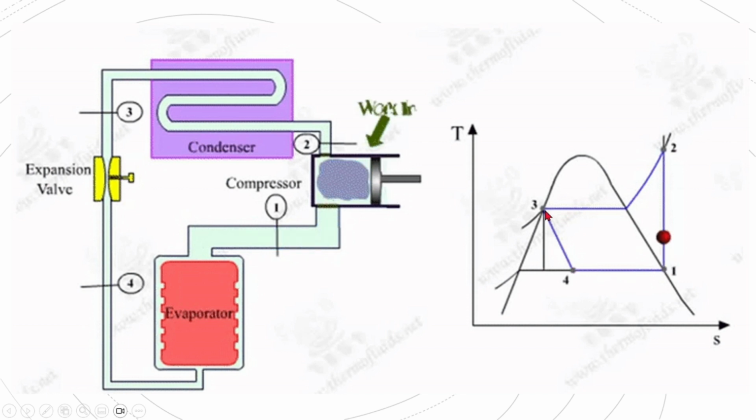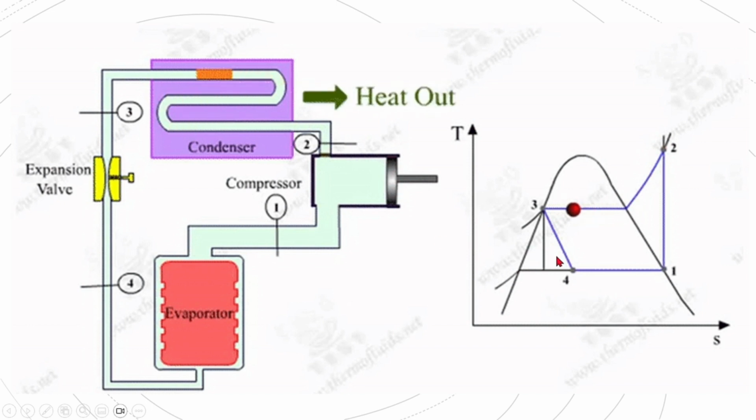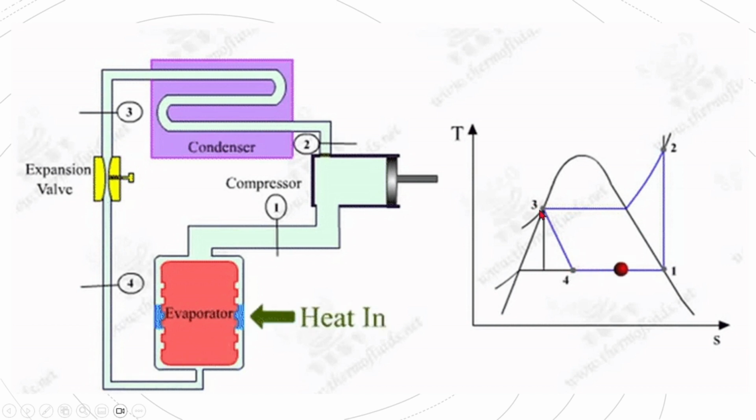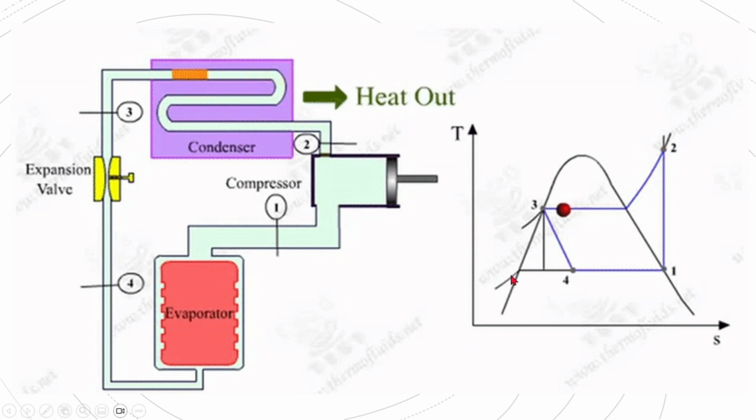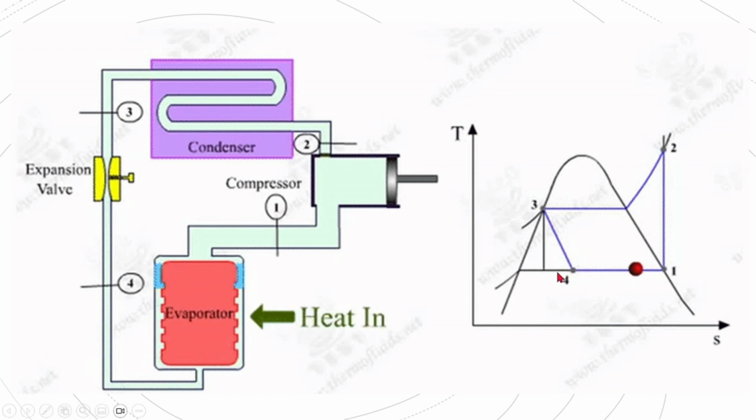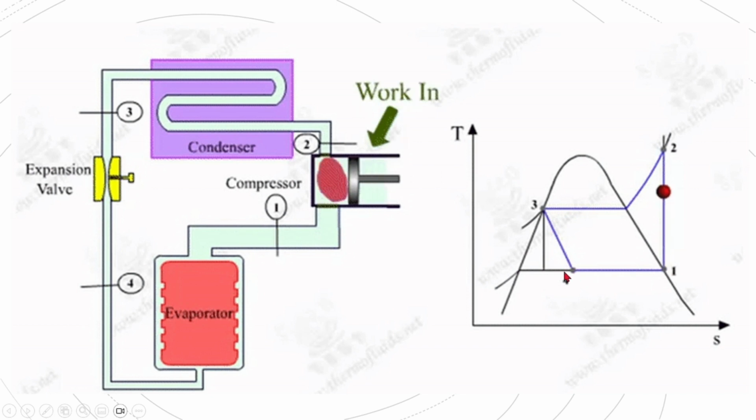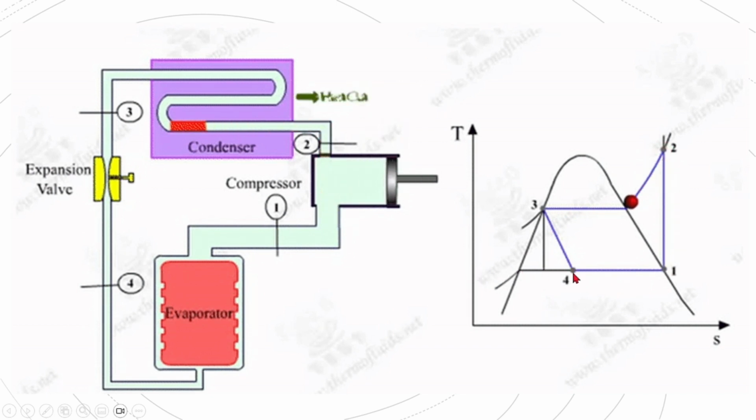So the pressure drops. As the pressure drops, the refrigerant starts flashing off. Flashing off means the phase change takes place, so that's why this graph moves to the right side from its original position. And there will be a reduction in the refrigerant effect, because this is the boiling temperature at this pressure, where in the evaporator heat transfer takes place. In the evaporator only the latent heat is involved, so the temperature comes up. The fourth point is in the evaporator, right?